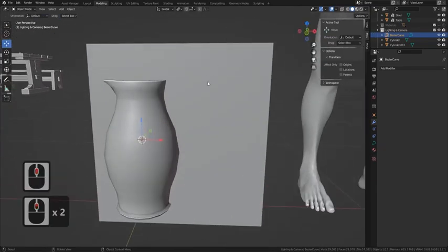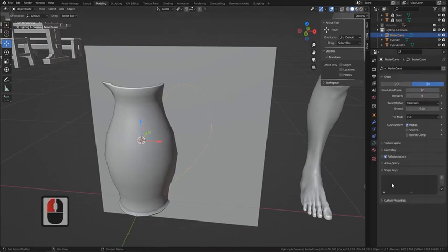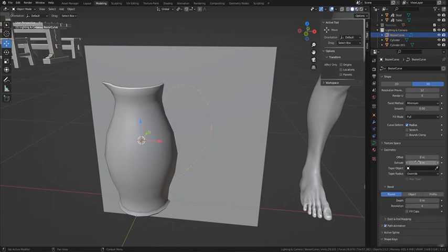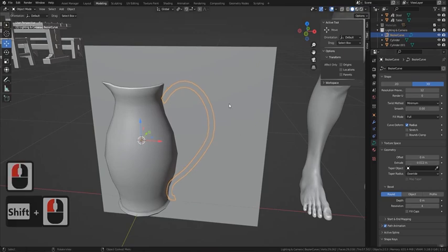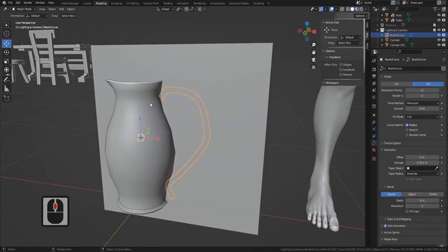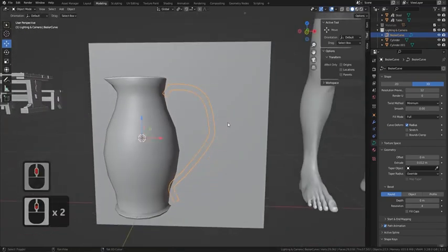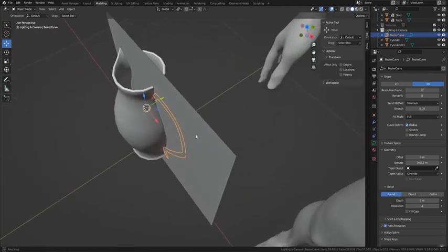Now, once you've got your curve in, let's see what it looks like, because if you're not happy with it, you can just draw in another curve. But what you want to do is come round, go to geometry and open this up, and you want to basically extrude it. Now, sometimes when you extrude it, it will be going the wrong way. Now, all you need to do is just press Tab, A to grab everything, Shift N, and what that'll do is it'll spin it round the right way for you, as you can see. Now, some of the points you might not be happy with, but don't do anything about that yet.